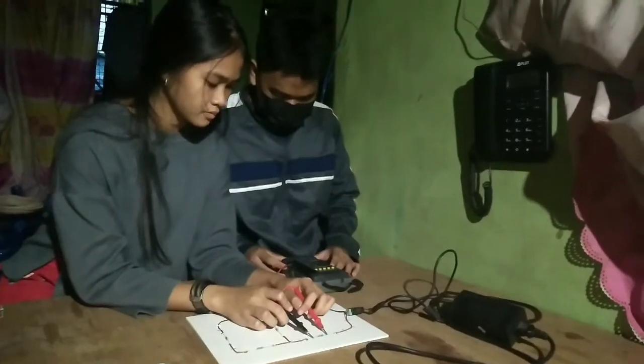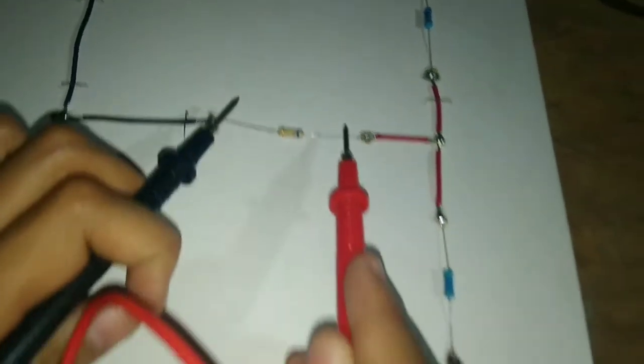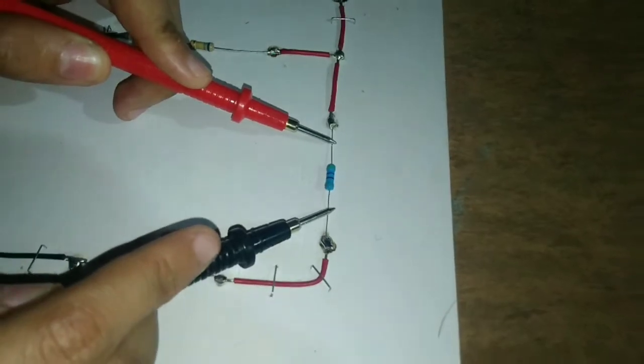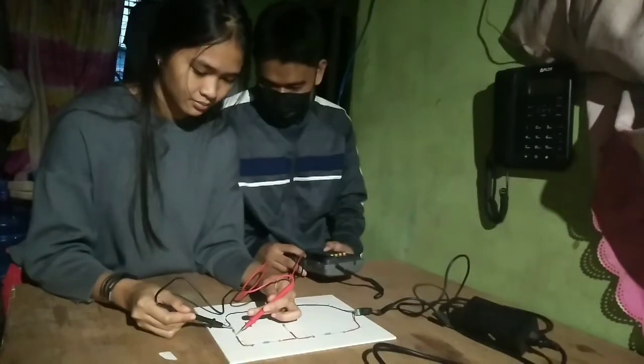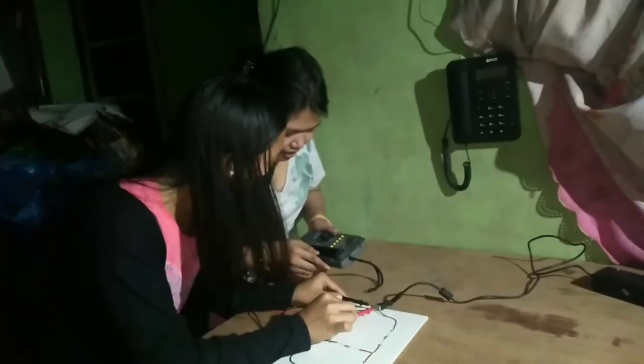At this point, we are measuring the actual resistance and voltage that are included in the circuit using the multimeter. If you're wondering why it isn't very accurate compared to theoretical measurements, it is because of the tolerance of the resistors.